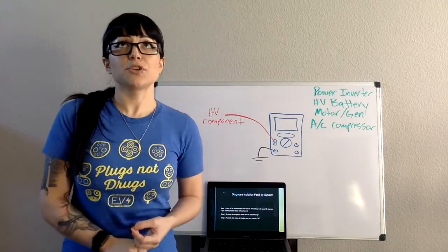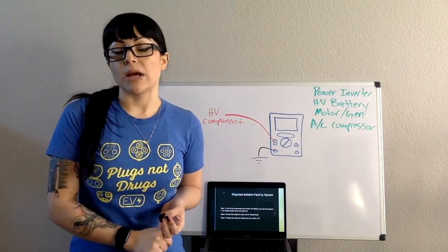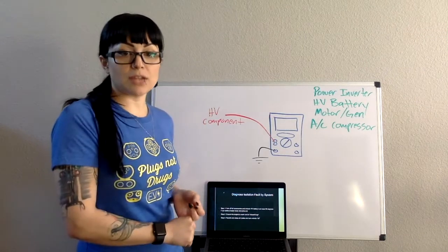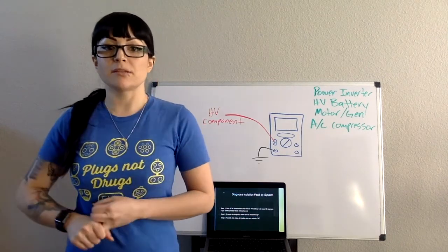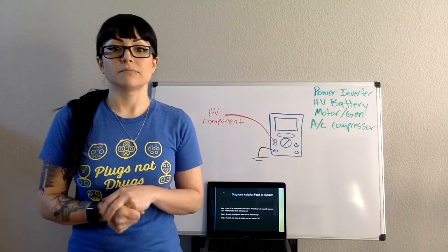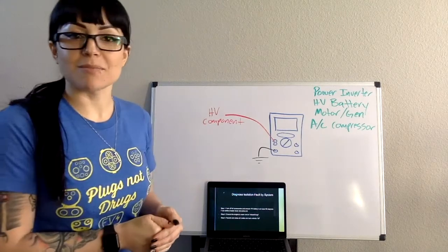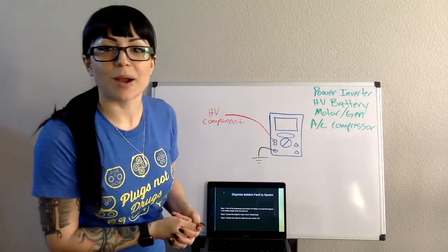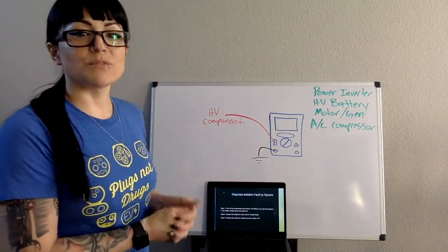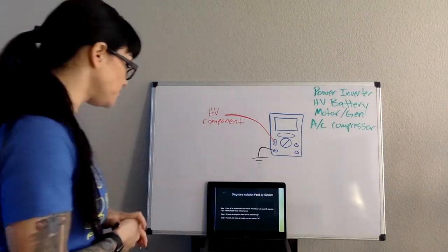We don't want the engine coming on unless we want it on or running. So we want to make sure that the engine is in closed loop and up to running temperature before this test has been performed, if you can. Sometimes the fault tends to come on prior to, so it won't let you. If we can, we want to try to make sure that the engine's warm.